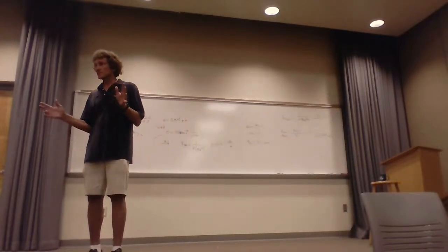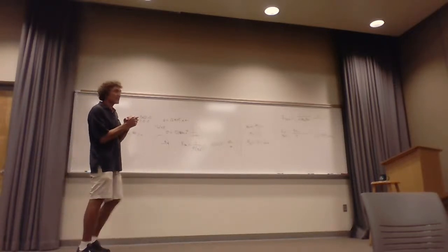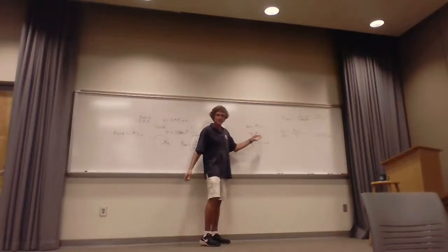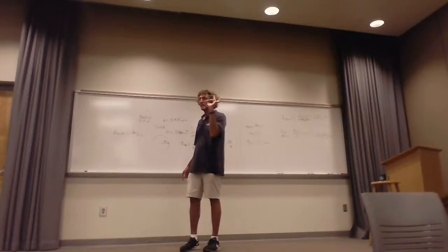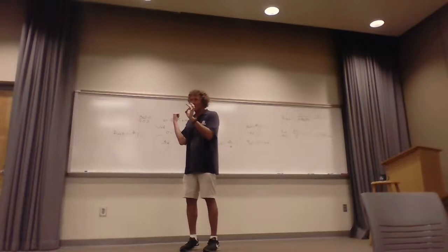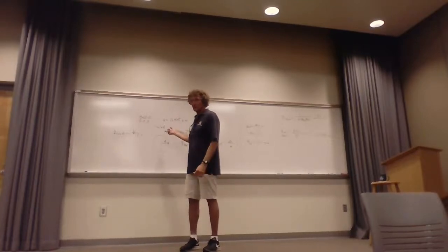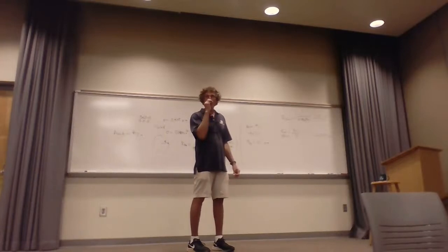Now, for AC resistance, this is my point. If you do AC resistance, you're going to find out the higher the frequency, the braid will be less. If you look at the actual cross-sectional area of the wire, it's the same. I mean, the actual diameter of the braided wire bundle is the same as the diameter of AWG 20 solid. Are you with me? And that's real important, because when you get AWG wires, it's the American wire gauge.